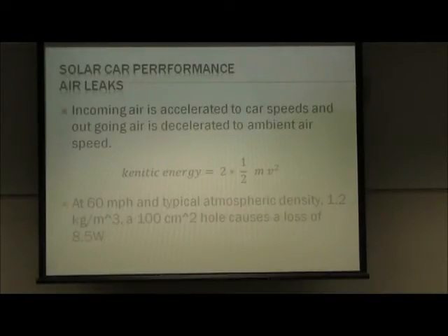And then when it goes out, you have to decelerate it. That takes energy. That takes power coming in. The kinetic energy is 2 times 1/2 mv squared, where m is the mass of the air you have to accelerate and decelerate, and v is the velocity of the car, assuming everything's flat.